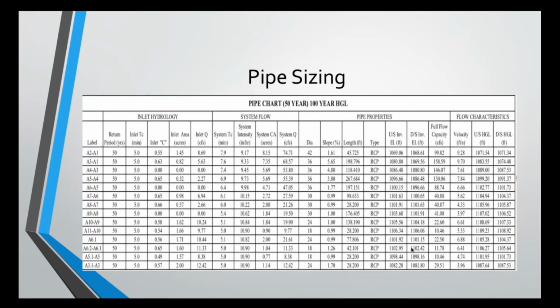The maximum velocity is 15 feet per second. The minimum time of concentration used to design is 5 minutes. All pipes are designed according to HSS. The minimum pipe size, spacing, and maximum length of pipe are determined using Article 21 of the Forsyth County Unified Development Code.